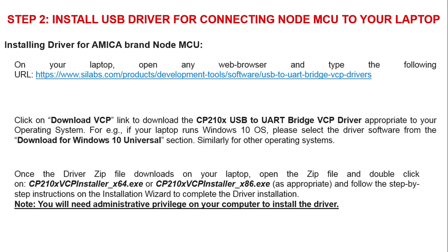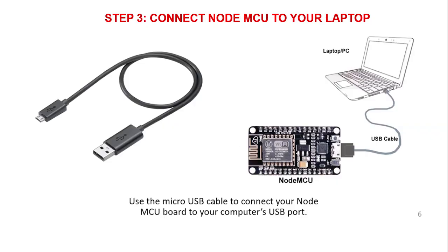CP210x VCP installer, either the 64 bit .exe file or the x86 .exe file, as appropriate for your laptop, and follow the step by step instructions. You will need administrative privilege on your computer to install that driver. If it is not installed, then it is directly installed. If it is already installed, then we can do one thing.